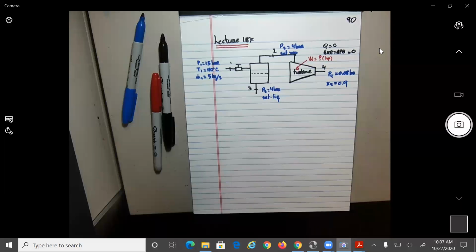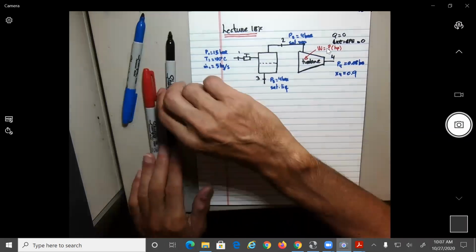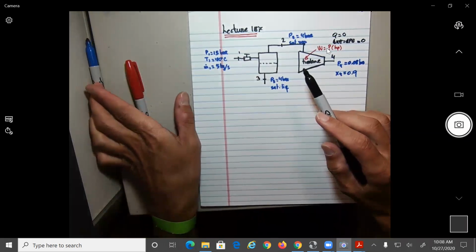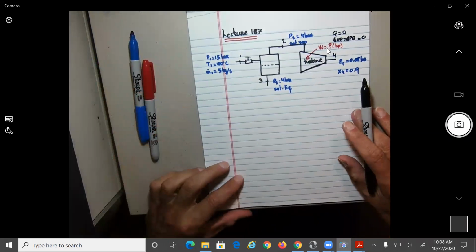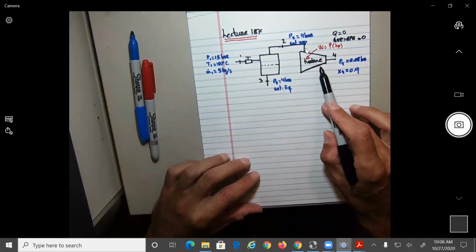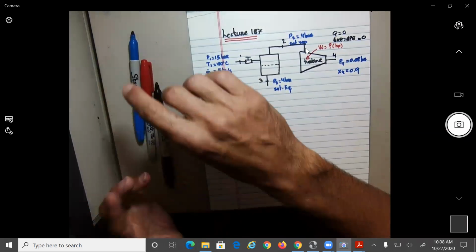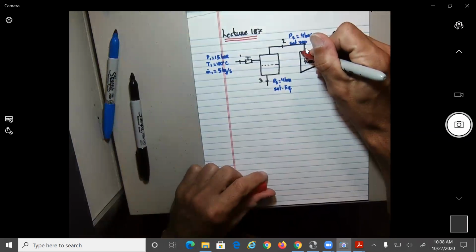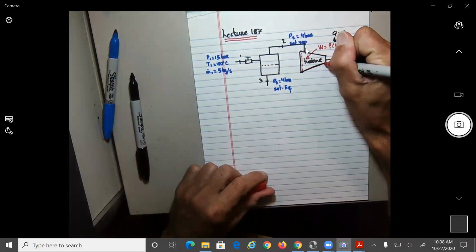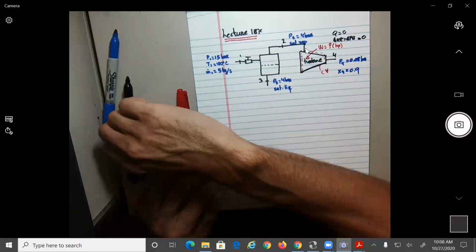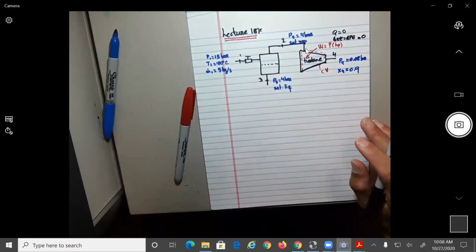There we go. Okay, so this is basically the graphic that I've done for this problem, and basically the substance we are dealing with here is water, no? Because they talk about saturated vapor and saturated steam. So what we need to find is the power in the turbine. The first thing I will do is select the control volume. So let's say I select this one as our control volume here. And then we see what data we need to find.